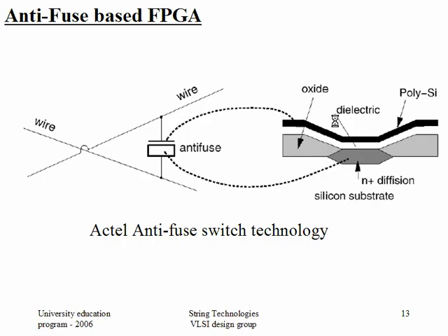What I have shown is from one company, Actel. Actel is also a big company, and they make many FPGAs. Actel flash-based FPGAs are more known than Xilinx and Altera solutions, meaning they are more expert in making permanently programmable FPGAs. But Altera and Xilinx give good FPGAs which are based upon SRAM.